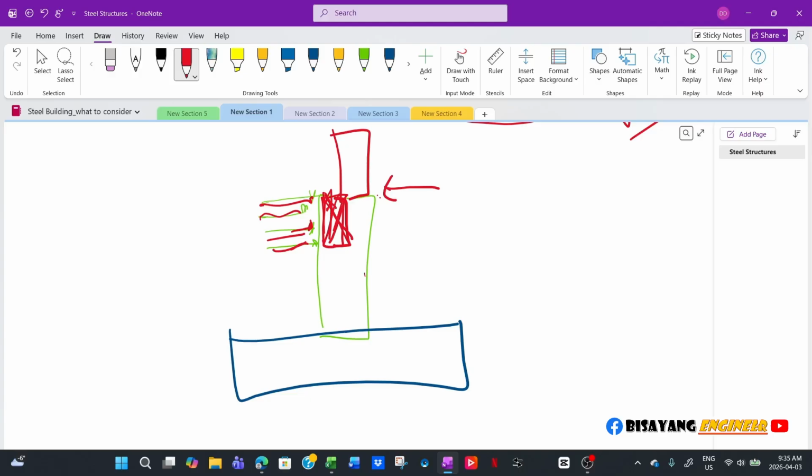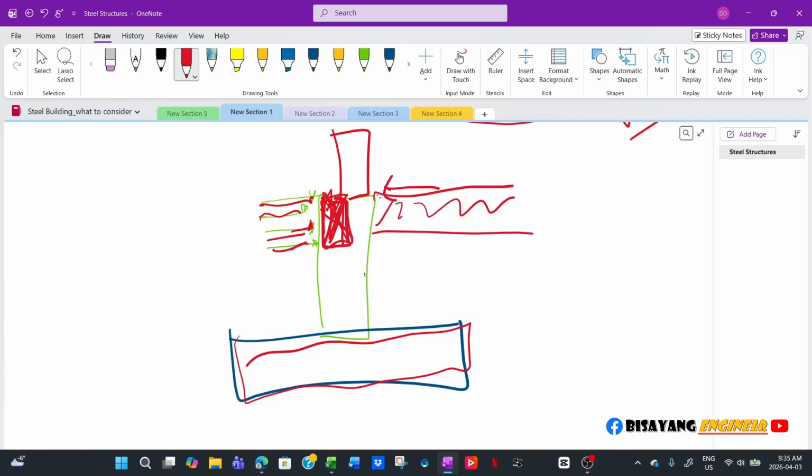That's why I have a project where I utilized this kind of foundation for a Prince building. I have this perimeter, and I designed it to resist the lateral load, because there is no pavement here. It's just gravel, because it's a cold storage, a lumber yard for storing timber. So this is just gravel, so there's nothing to support it, you cannot utilize it.